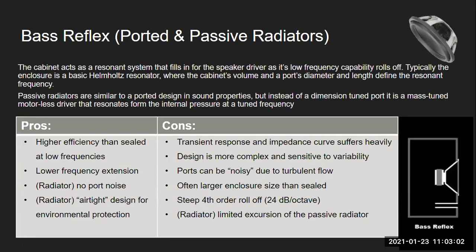So a more advanced design, which is probably one of the most common today, is the bass reflex design. It's interesting. It's effectively using a Helmholtz resonator to fill in as the speaker driver's bass response starts rolling off.